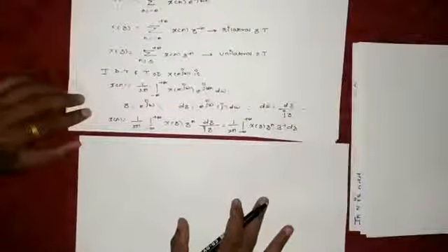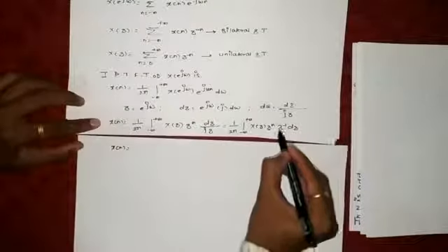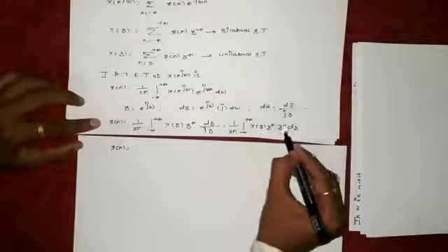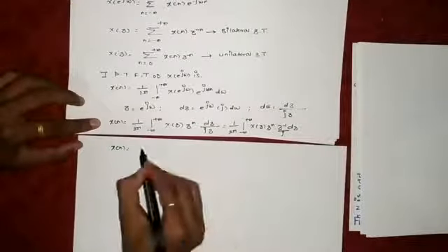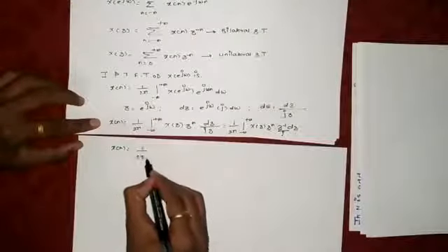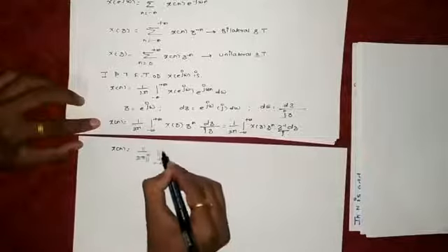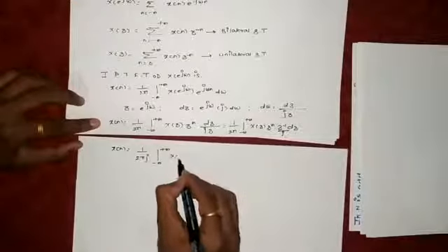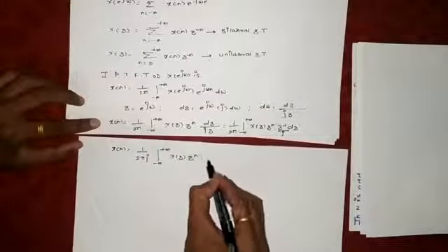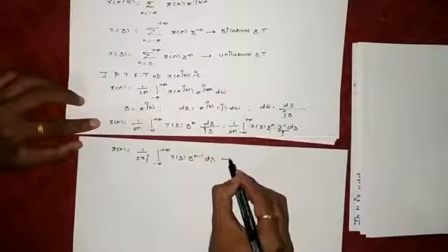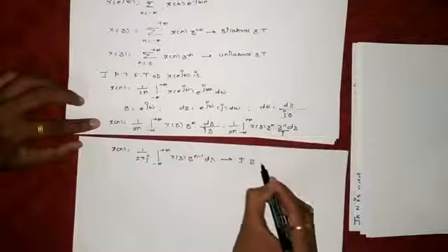So from that we can get the inverse Z transform equation as x[n] equals, j remains, so you can take j over here. So this is 1 upon 2 pi j integration X of z into z raised to n minus 1 into dz. This equation is known as the inverse Z transform.